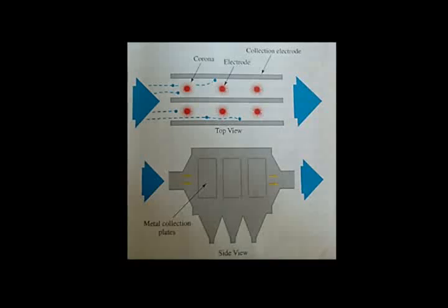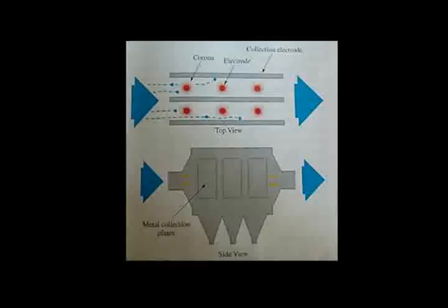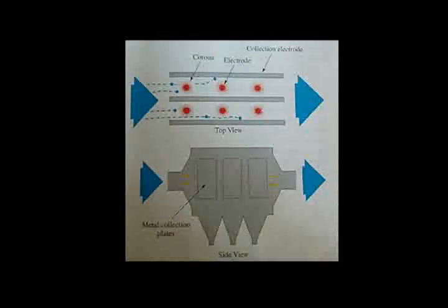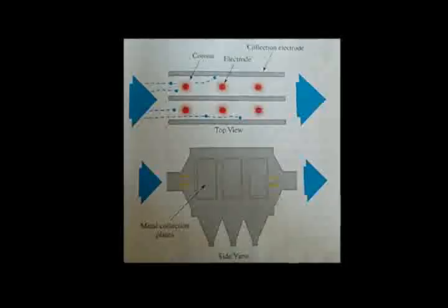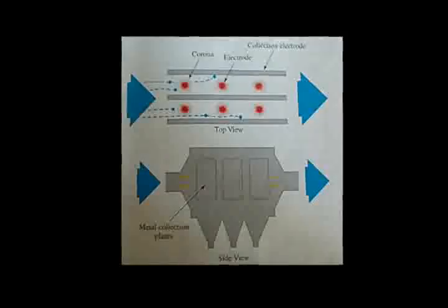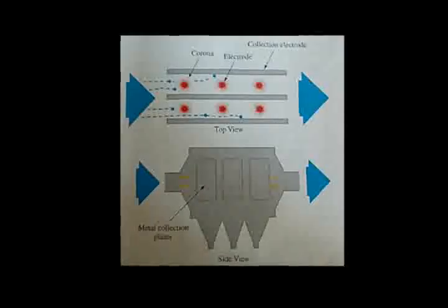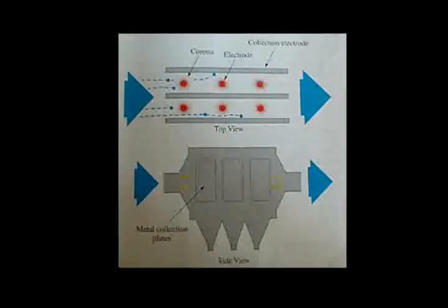Most precipitators are divided into two parts, a charging section and a collecting section. The charging section can be designed in many different ways. It can be an assembly of parallel rods or wires, a screen pattern or bank of piping. Regardless of the physical design, the electrical principle is the same in all cases. Figure 1-11 illustrates the operation of the electrostatic precipitator.